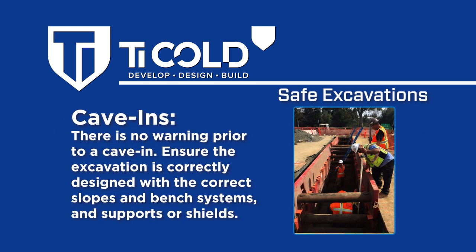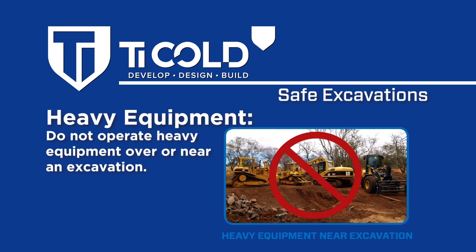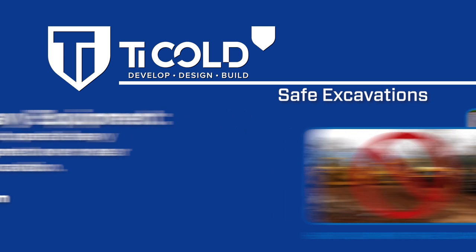Cave-ins. There is no warning prior to a cave-in. Ensure the excavation is correctly designed with the correct slopes and bench systems and supports or shields. Heavy equipment. Do not operate heavy equipment over or near an excavation.